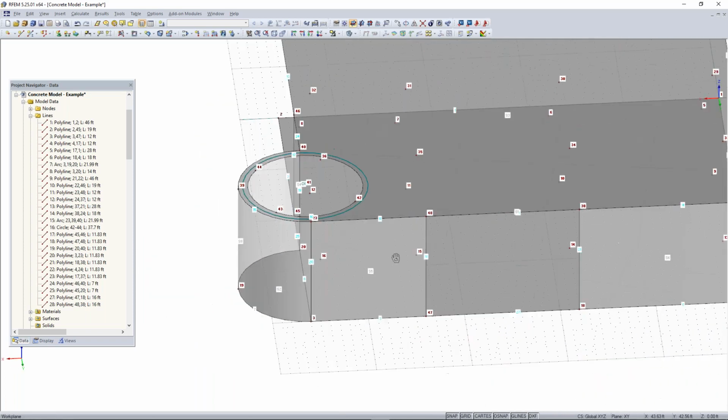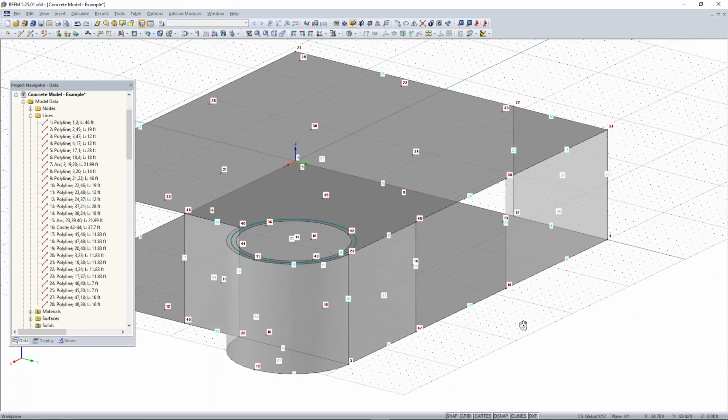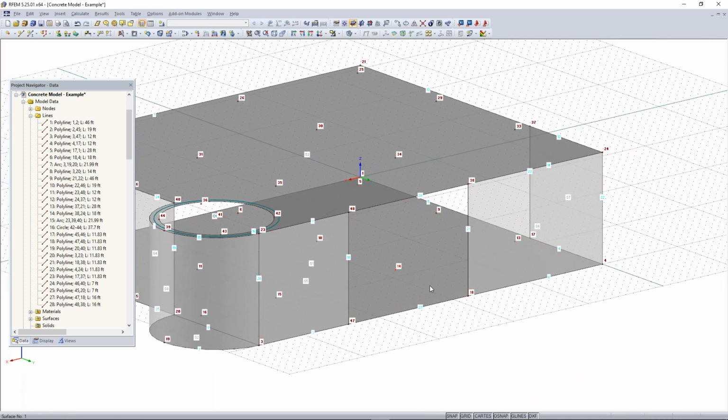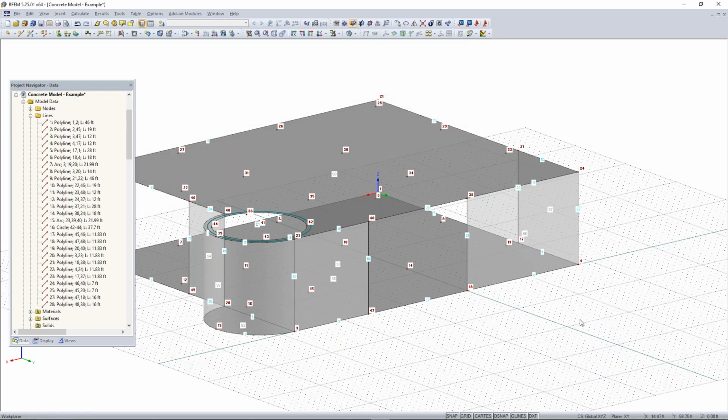So now we have basically all the walls to connect our floor slab and our ceiling slab. We're actually missing one more in the center, which will be our load-bearing wall. So what I need to do now is change the origin of our work plane to node 18 here. To do that, you can go up here to the button called Set Origin of Grid / Work Plane. And then we can select node 18.